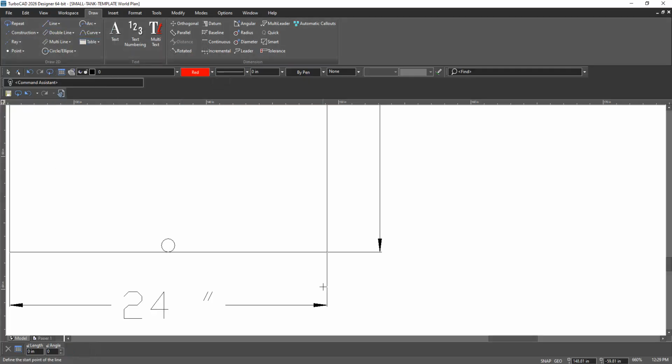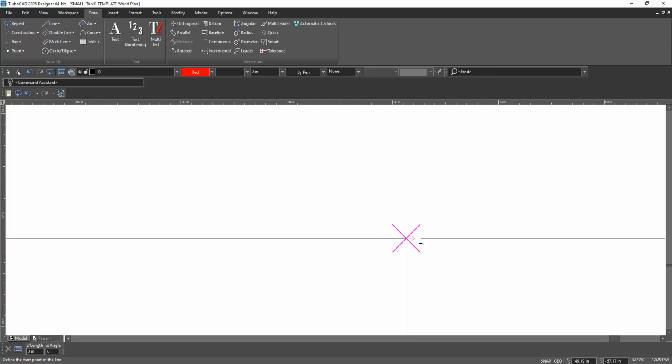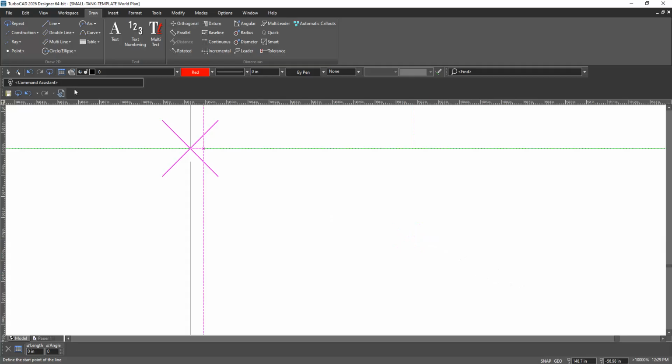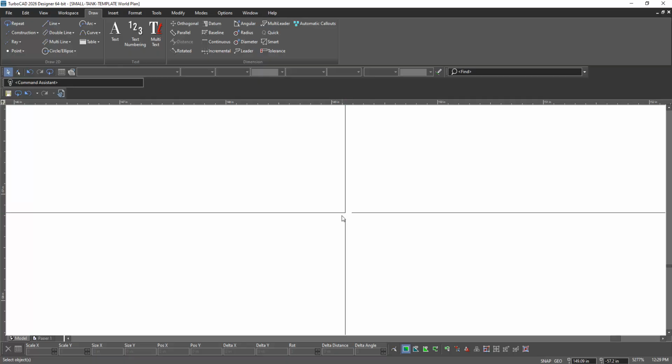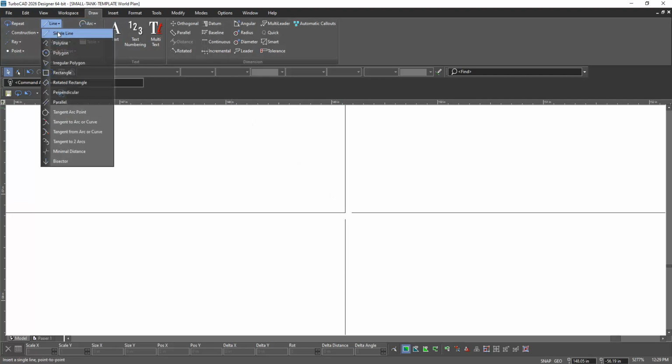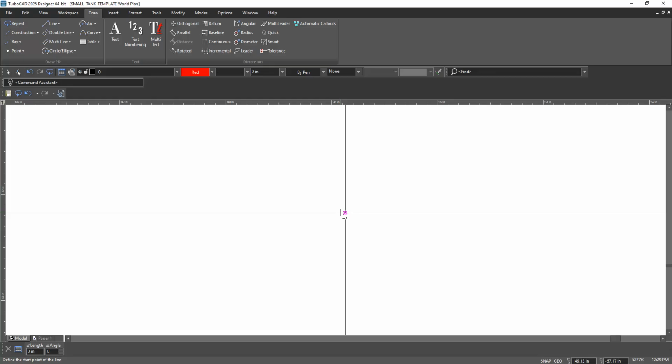We're going to make it red again. We're going to come over. Now remember, zoom way in because you don't want to start that on that dimension line. You'll mess everything up. You want to zoom way in, start it in the bottom corner of your actual thing that you're drawing here. Do a line, single, red, start in that corner, pull outward 2 inches, 180 degrees. So you tab 2, tab 180, enter.